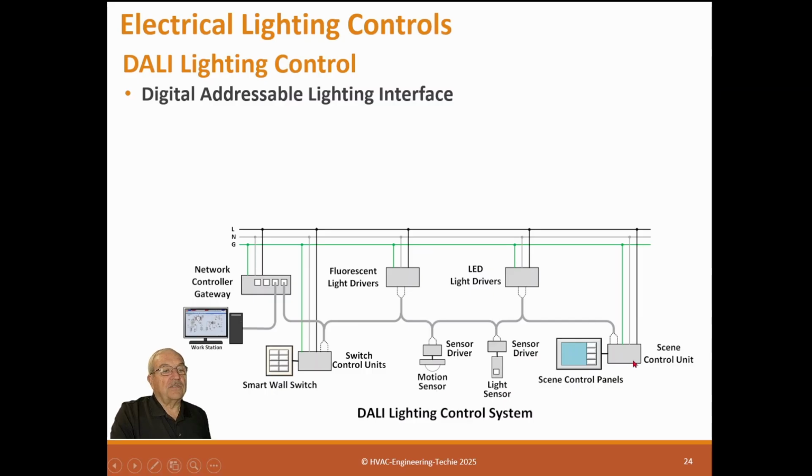This is a scene controller. So you could say, I push a button, I want a scene where the lights are dim, it's really comfortable, it's more for a party atmosphere, or I want it for a work session, it's going to be bright. You can have different scenes in here you might want it to have, and that controller does that. And then here you have the light sensor, that's on a separate driver. You can have a motion sensor, those are on separate drivers.